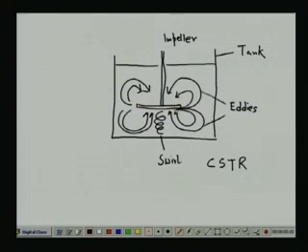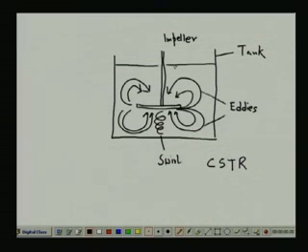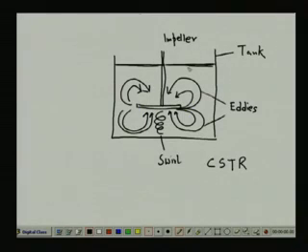There are various types of reactors. You can have a bubble column reactor, you can have a CSTR, continuous stirred tank reactor. Now, the basic principle is that you increase the blade speed, because this impeller is rotated by a motor. If you increase the motor speed, what will happen? One thing you must know is that it is very difficult to dissolve oxygen in a liquid. The only place where the oxygen will be dissolved is through this top surface.